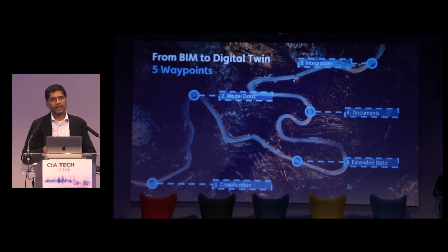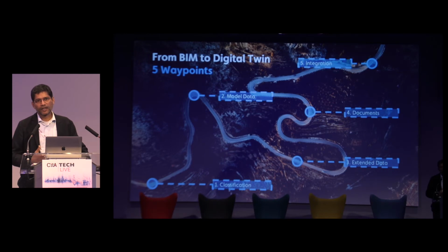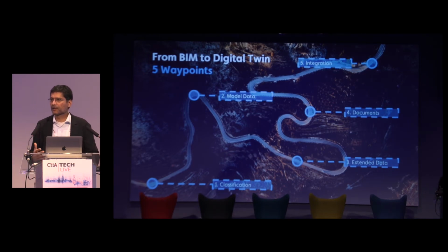The good thing is integrations are becoming easy. Even with building automation, there was a time when integrating into a Siemens or a Johnson or a Honeywell or whoever, Cylon controls, any BMS system was a challenge. Today, with standards like BACnet, which has always been there, and more importantly, standards like Haystack and Brick, it's very easy for us to know what data point does this represent.